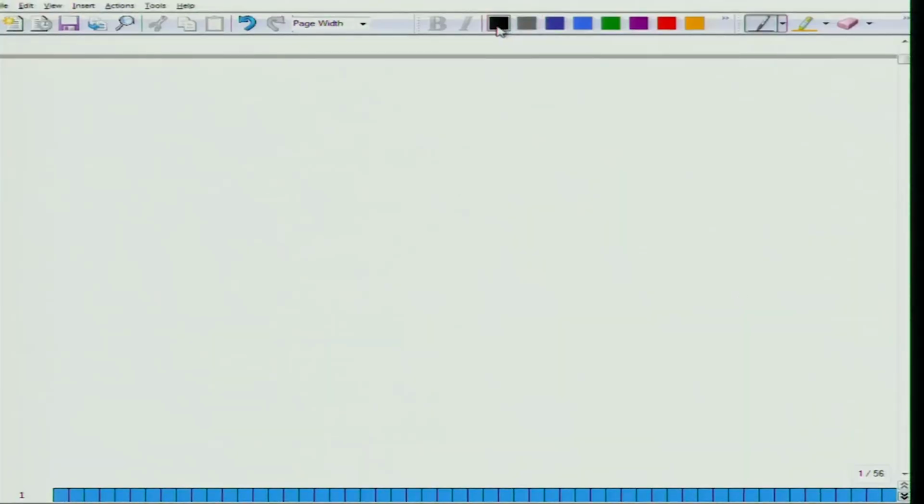Now we are going to see a more general, in fact a more capable, modulation scheme, which can take not one of two levels but one of M possible levels. So each digital symbol A naught can take one of M possible symbols. Now let us represent these M symbols. Since there are M symbols, the number of bits equals log M to the base 2.